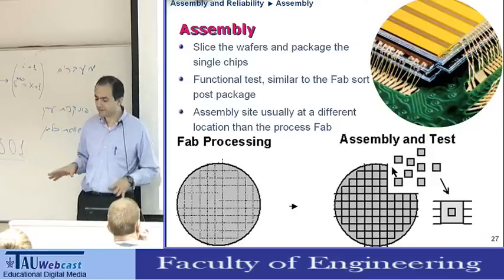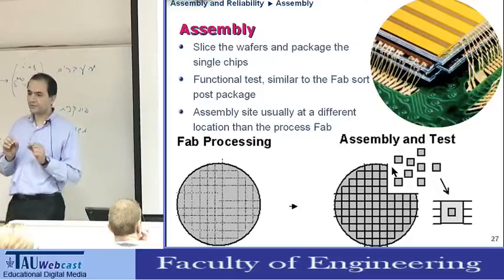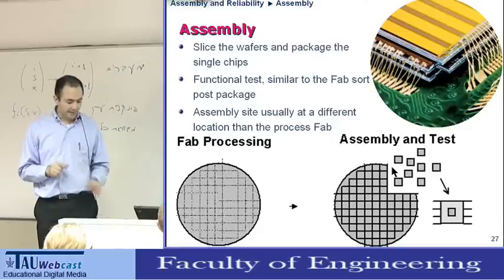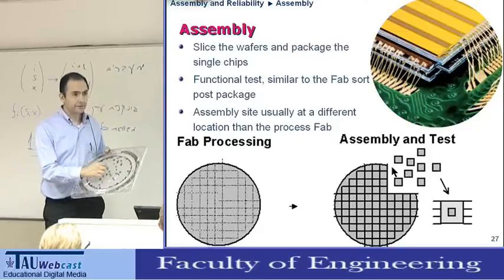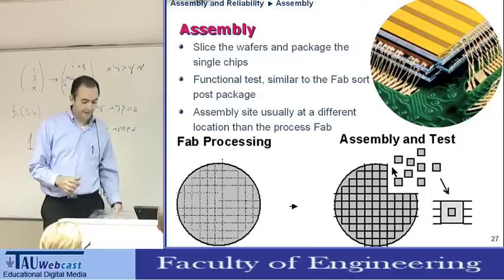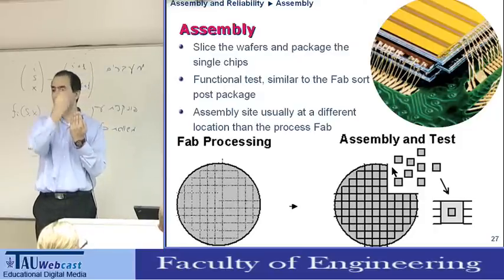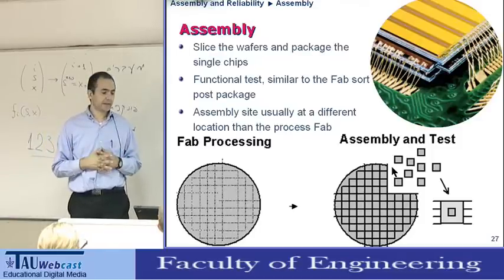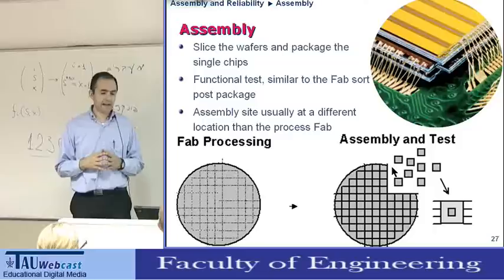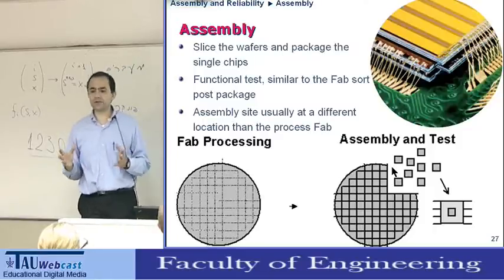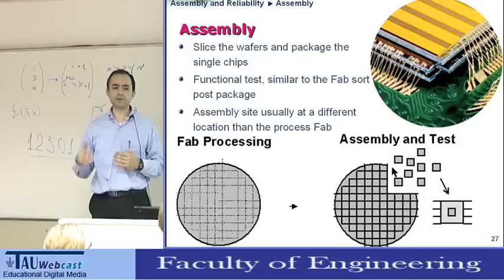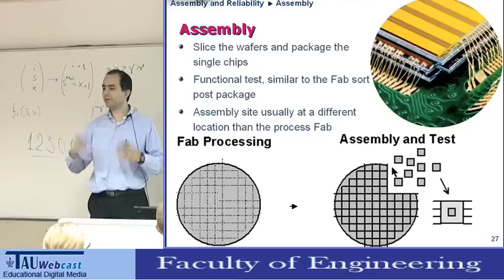So again, just to summarize, we have structures which are very simple: transistors, capacitors or resistors. They are placed in the space between two adjacent dies. Later we saw this, so there's no mark left for the product. Any variation on these electronic structures which exceeds what we call the control limits needs attention. If it exceeds what we call the dispo limit, we throw this away.